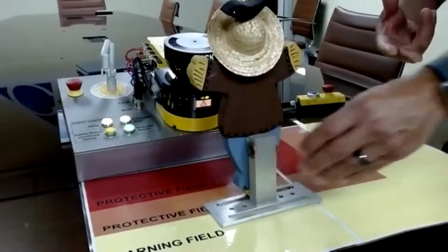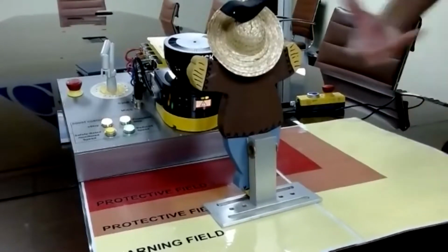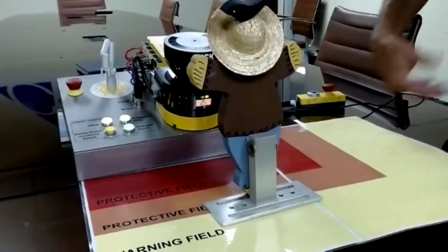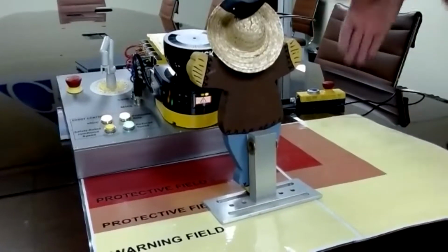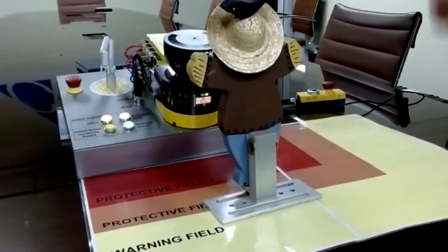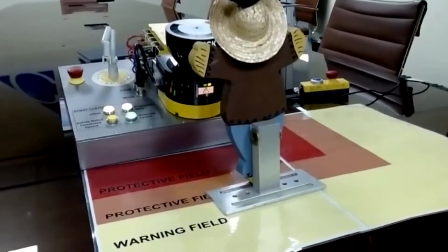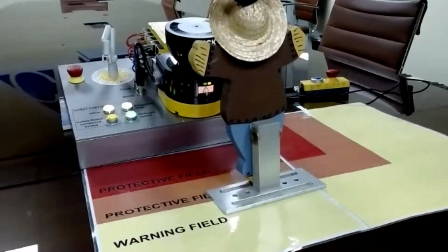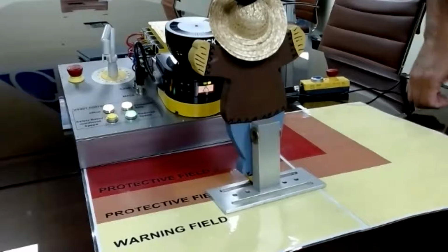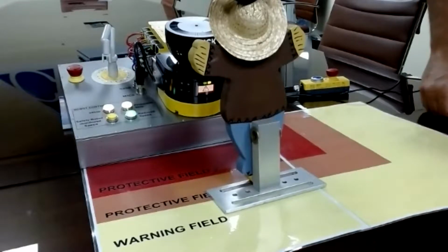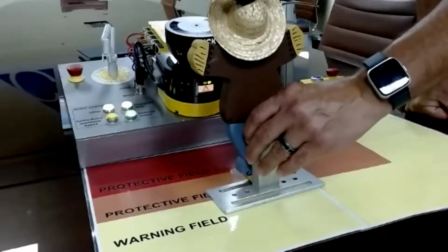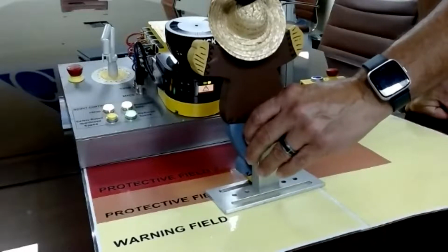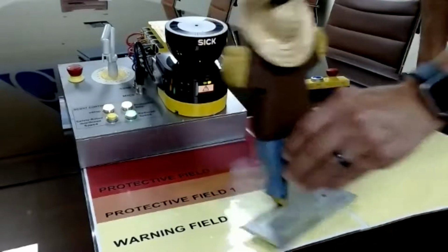That does 2 things for you. It increases your productivity because now at least I'm getting some productivity. And 2, it reduces wear on your robot because I'm going from stop to slow speed and then from slow speed to high speed, instead of going digital from high speed to stop and stop to high speed. It's like driving your car and tapping the brakes ahead of time. You're already slowed down, and then gradually increasing your speed, you're going to increase the productivity and you're going to increase the longevity of your robot.